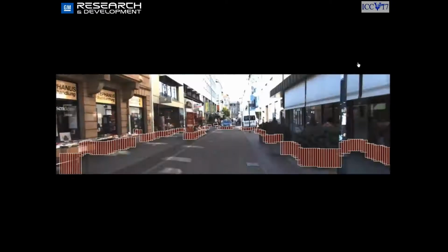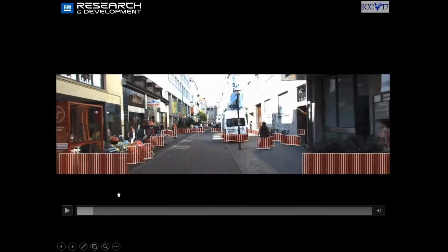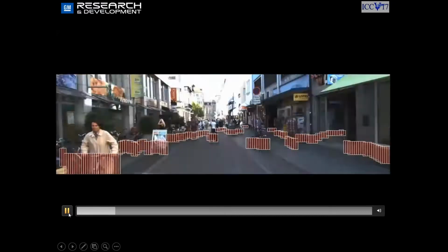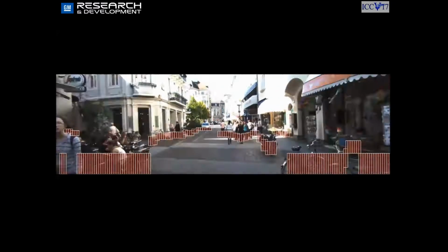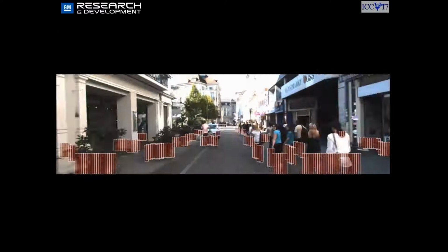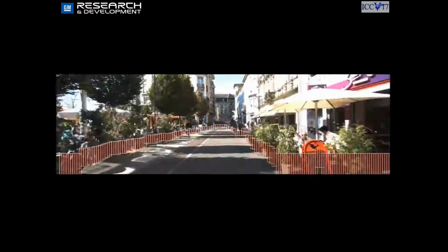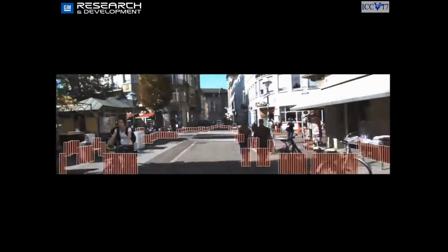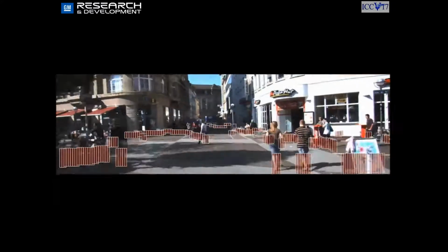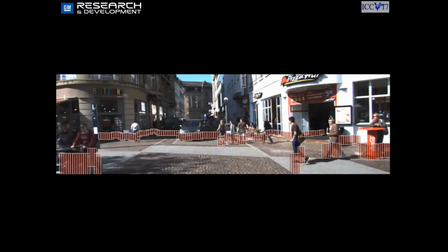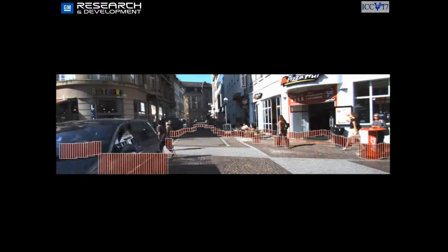And in general, this is the type of result we obtained with this approach. So you can see that just from using automated ground truth, we could reach some nice monocular camera-based general obstacle detection, but you can see that it's very noisy and it makes many mistakes that the LiDAR would not make.